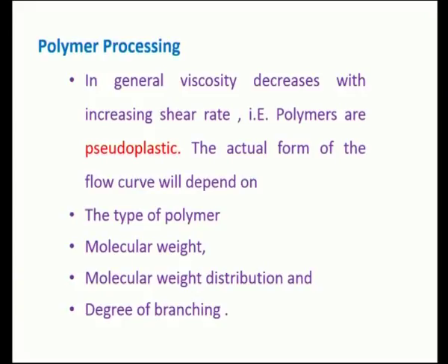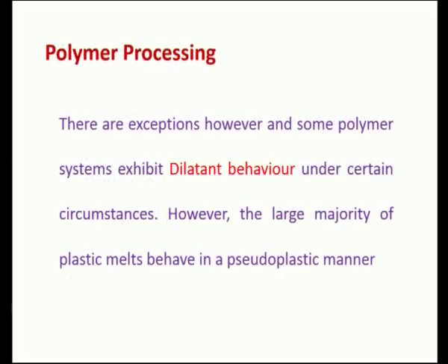The actual form of the flow curve, which here refers to the rheogram, depends on the type of polymer, molecular weight as we have discussed earlier, molecular weight distribution, whether it is widely distributed or narrowly distributed, and degree of branching. And then there are a few exceptions from pseudoplastic, which come into the dilatant system. Dilatant behavior simply means that when you increase the shear rate, the viscosity increases. Therefore, dilatant polymeric systems are not commercially significant.